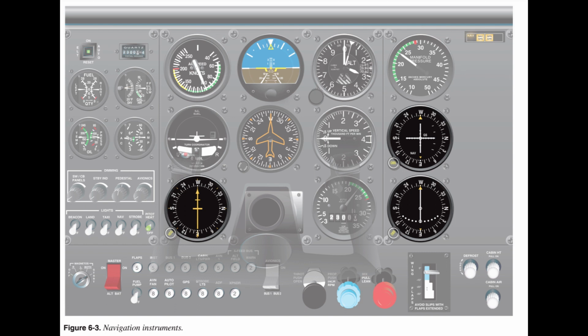Experience in an aircraft teaches a pilot approximately how far to move the throttle to change the power a given amount. Power changes are made primarily by throttle movement, followed by an indicator crosscheck to establish a more precise setting. The key is to avoid fixating on the indicators while setting the power. Knowledge of approximate power settings for various flight configurations helps the pilot avoid over-controlling power.